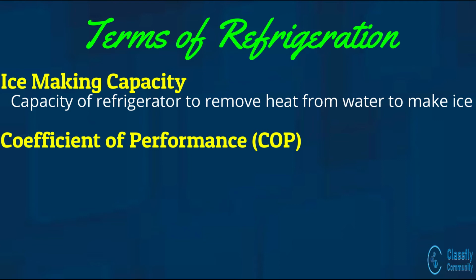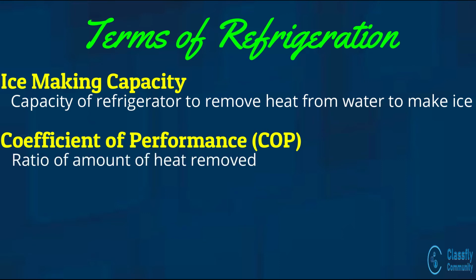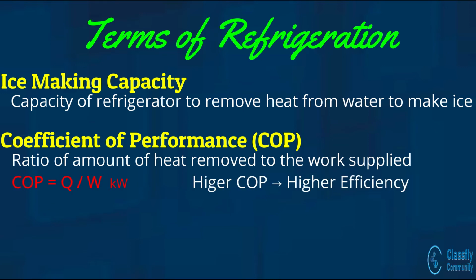Well, the performance rate of the refrigerator is measured by the COP. COP is defined as the ratio of amount of heat removed from the given space to the work supplied for the heat removal. Hence, COP can be given as Q by W and is expressed in kilowatts. It is important to note that the higher the COP, the more will be the efficiency of the device.